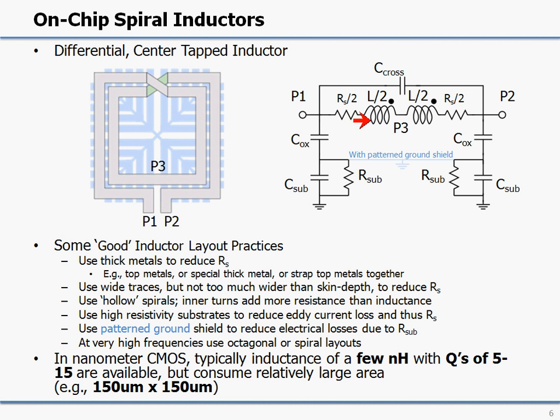Electrically, we indeed find that it has inductance. Also, however, we see that there is series resistance in the structure because of losses in the wires, and losses in the substrate that also result in energy losses and reduced Q. And we also notice that at higher frequencies, the signal might bypass the inductor through capacitance due to the crossover here, or interwire capacitance in the windings.